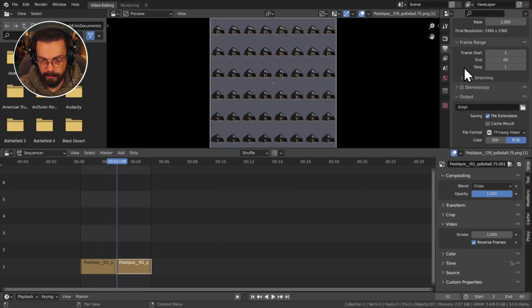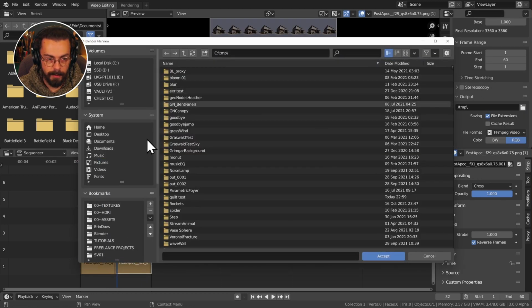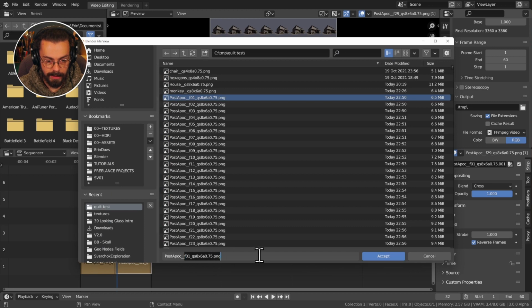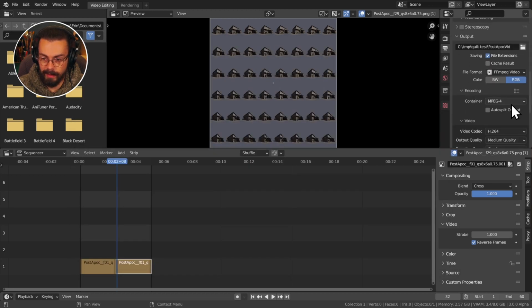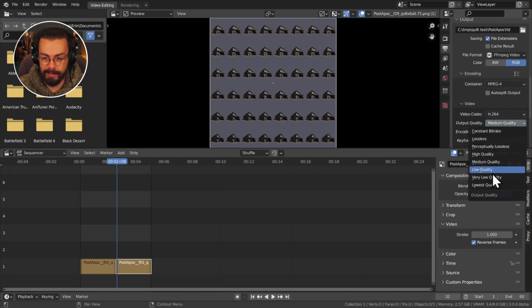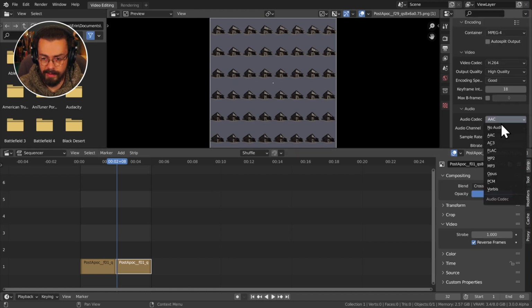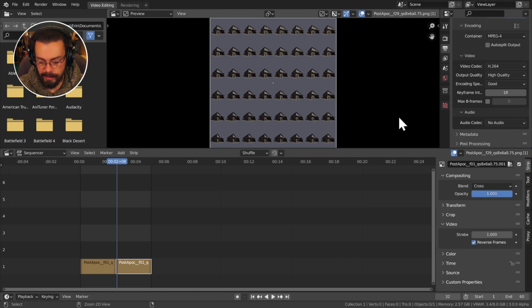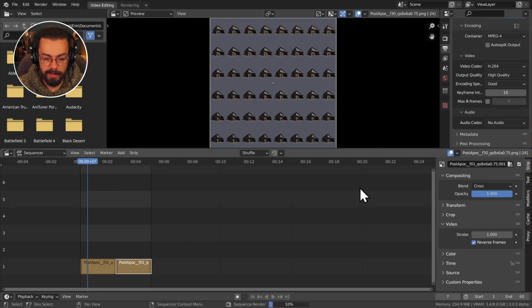And again, I'm just going to be rendering this out. So I'm going to find my quilt folder. Let's call this one Post-Apocalyptic. And we're going to be doing an FFmpeg. Encoding is going to be MP4. Importantly, MP4 H.264, and let's go ahead and set this to high quality. I can turn off audio, that's fine. And then just hit Control F12 and it's going to render out your animation.